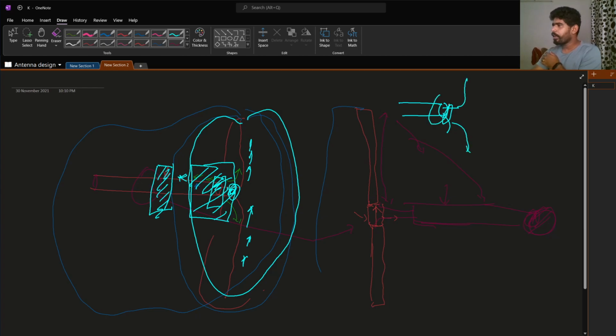You have to put the ferrite core here, and so this will attenuate the currents going through the shield; it will provide more impedance to the currents going through the shield. So again this pushes the currents to the actual antenna, and this also you will get some good. But balance is always good, because it's not attenuating the signal.